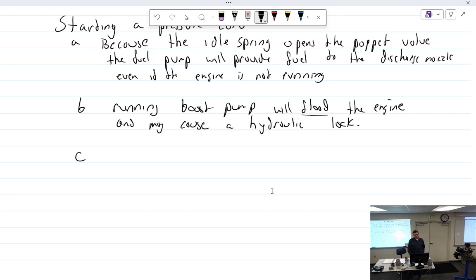So we're trying to hand prop this thing, we're getting nothing, and fresh overhauled cylinders and everything. And finally, the owner shows up, who was 80-some. He's like, no, this is what you're gonna do. Come on, and he tells me, I'm in the cockpit, all right, quarter throttle. Mixture here, key off, and he pulls it through a couple times. Now you're going to put the key in, and you put the throttle right here. Ready? Go. And this thing starts, and it goes like 1,500 RPM, and I don't see the guy anywhere.